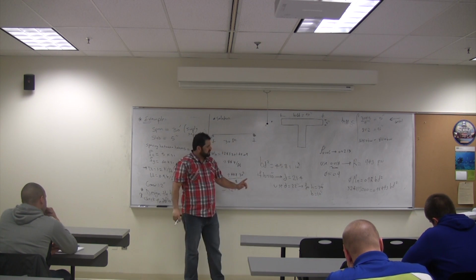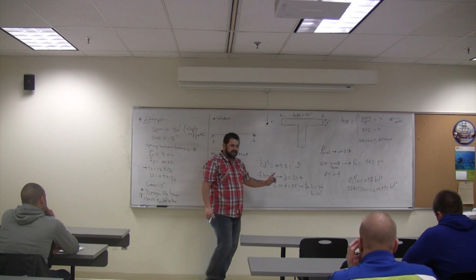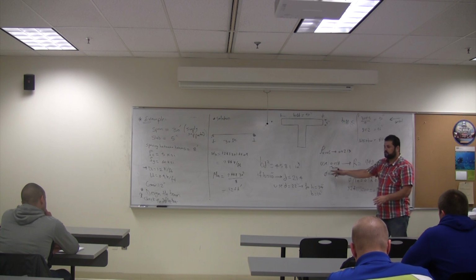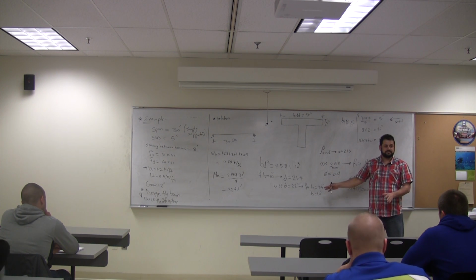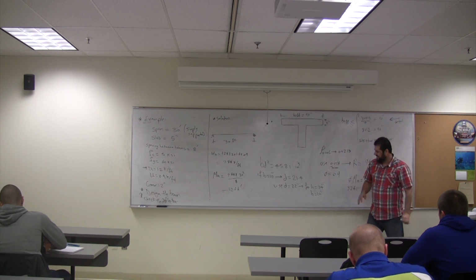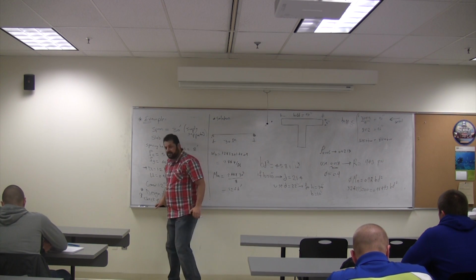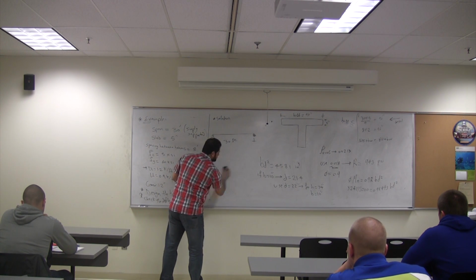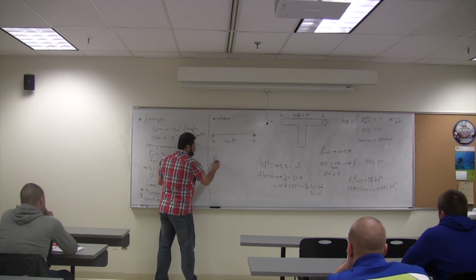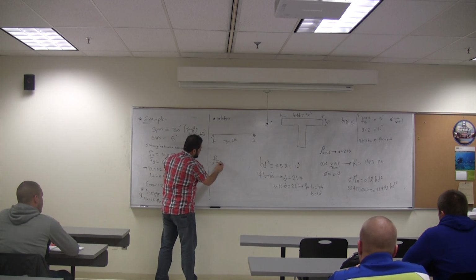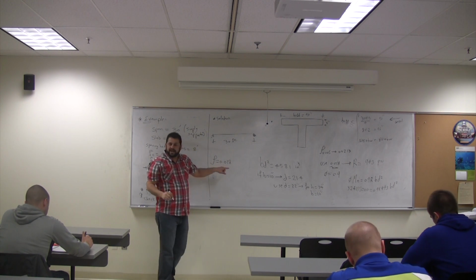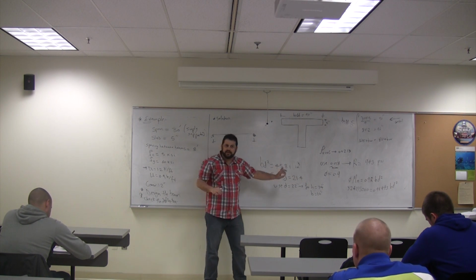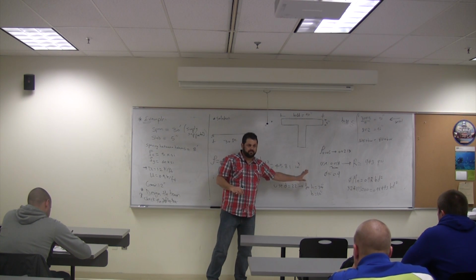Now you can say, so what should I do to calculate the area of steel? Should I multiply this rho by the 22 or by what? Look, what rho do we use? What is our rho? 0.018. That rho gives what we need for b equal 10 and d equal 21.4.